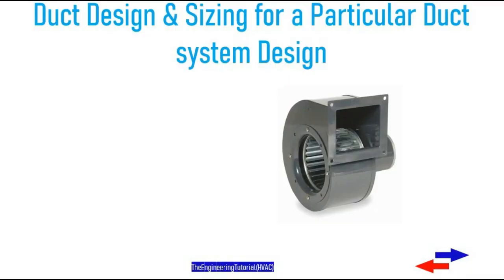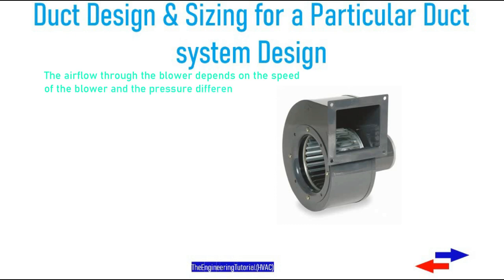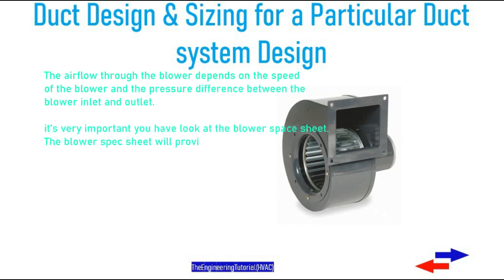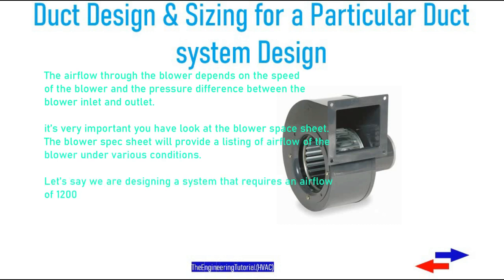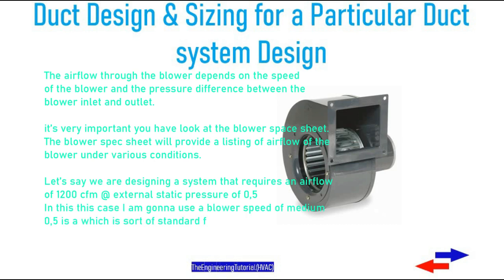The airflow through the blower depends on the speed of the blower and the pressure difference between the blower inlet and outlet. It's very important that you look at the blower spec sheet. The blower spec sheet will provide a listing of airflow of the blower under various conditions.